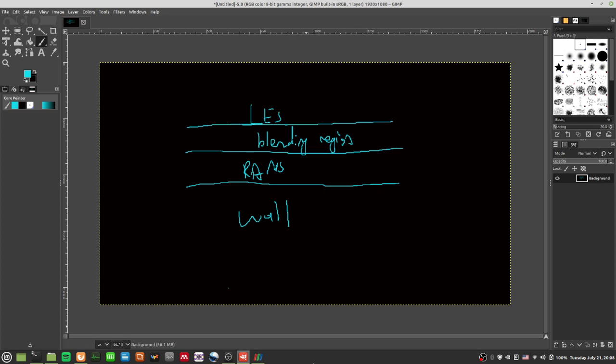And why is it called large eddy simulation? If you think about turbulence in general, there are big fluctuations and there are small fluctuations. The small fluctuations are the ones that make it so difficult to simulate all the turbulence. And 80% of the energy, by and large, you can capture in the large simulations, the large eddies.